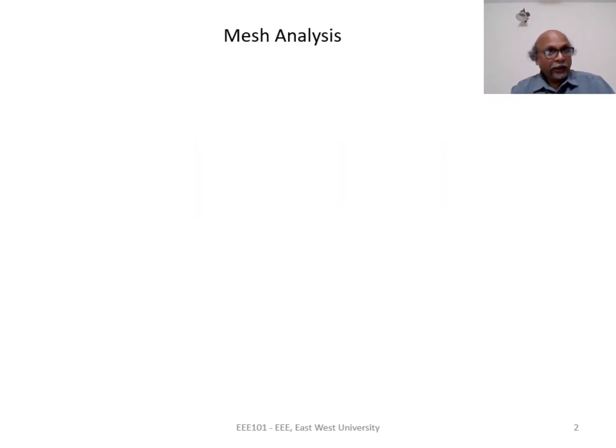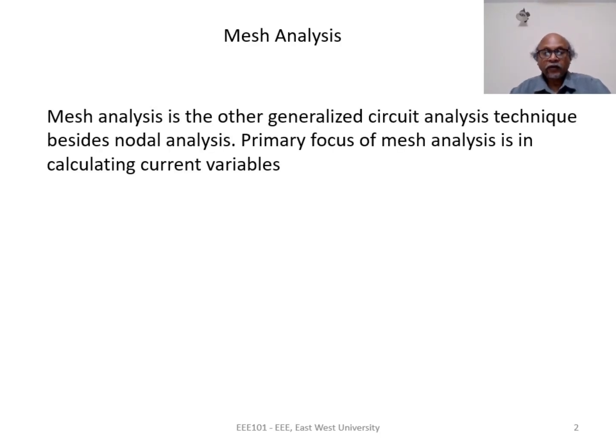We already know that there are two generalized techniques for solution of electric circuits, and we have learned already about nodal analysis. Mesh analysis is the other generalized technique for circuit solution. In nodal analysis, we saw that the primary focus is on the voltages and the node equations are based on KCL. In mesh analysis, the primary focus is on current variables and the mesh equations are based on KVL.